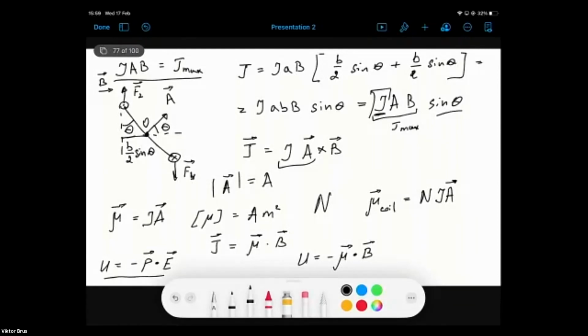The resistance of this coil is very small and can be neglected compared with the resistance of the electric circuit. And that's why there will be minimum voltage drop over this measuring equipment, this ampere meter. So it will give us quite accurate results in measuring the magnitude of electric current. And obviously it directly applies the interaction of magnetic field and conductor with electric current, which we discussed during this lecture.